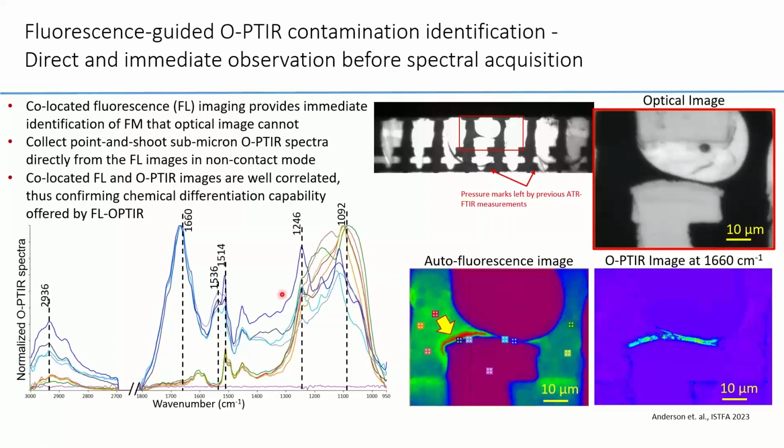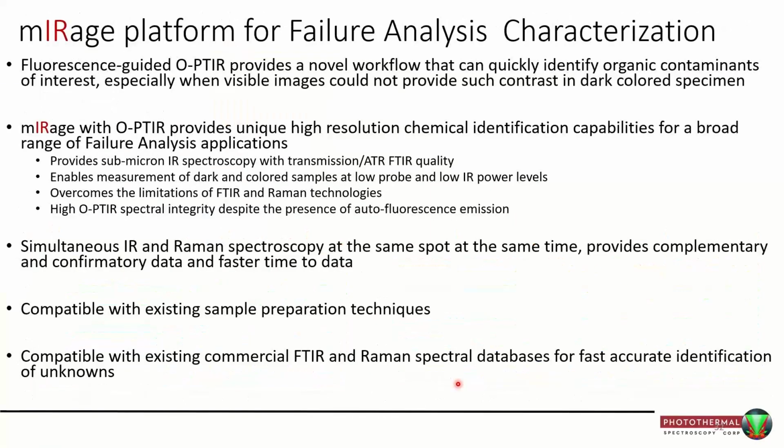And we can see that these blue spectra have these characteristic peaks. Now, if you're familiar with biological spectra in the infrared, you can almost be certain that is some sort of biological contamination, maybe protein, skin flake, and the like. If you do single frequency imaging at that 1660 peak, which is the strongest of those protein bands, it really shows you clearly how this is all along that interface where these two components touch each other. And I think that was the end of my application examples.